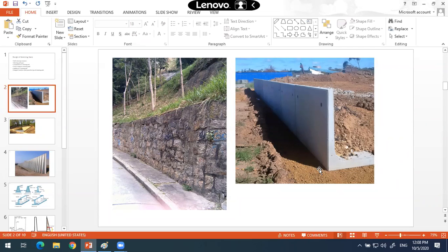Toe slab is missing. I may avoid providing the toe slab. Design will change, but sometimes it requires you to avoid providing a toe slab. Your boundary may be here itself. You have to stop your retaining wall here. You cannot make encroachment in the next area. So there, the toe slab has to be avoided. Situations may arise. So here, the toe slab is prevented.